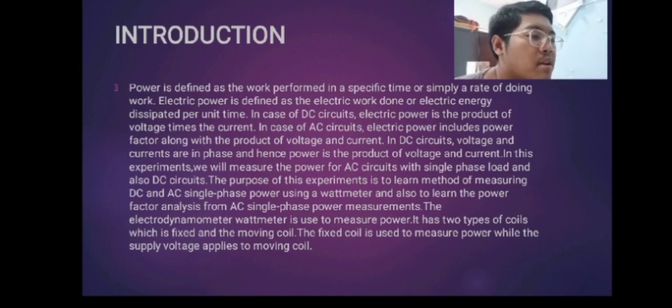The purpose of the experiment is to learn the method of measuring DC and AC single phase power using a wattmeter, and also to learn the power factor analysis from AC single phase power measurements.